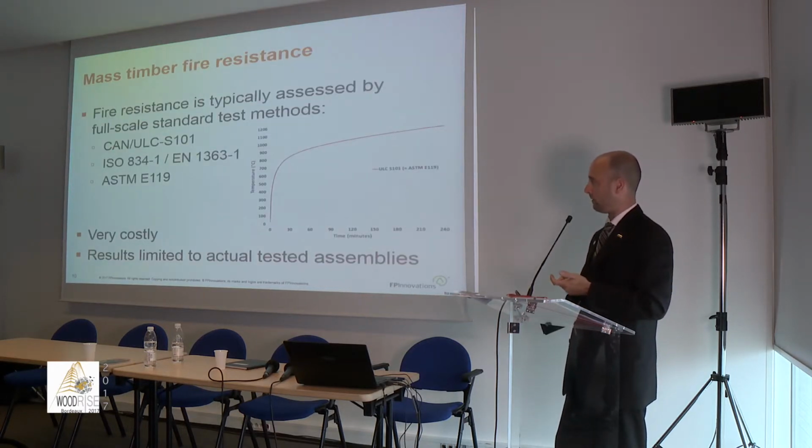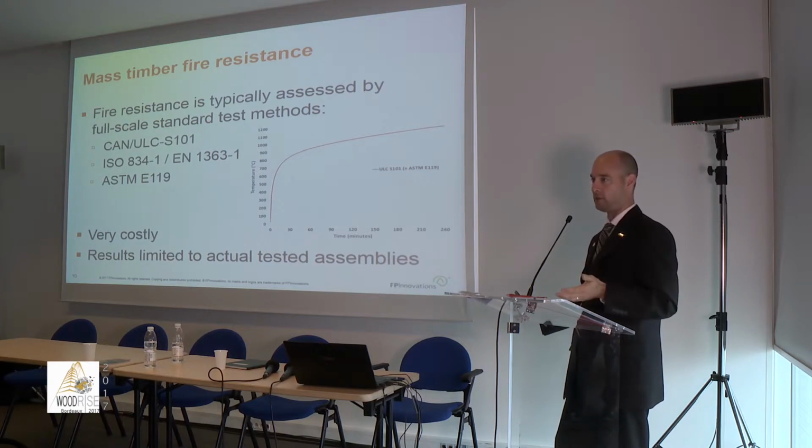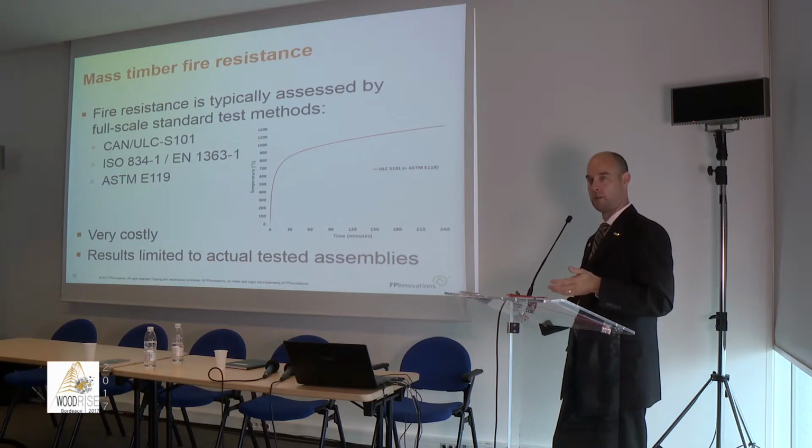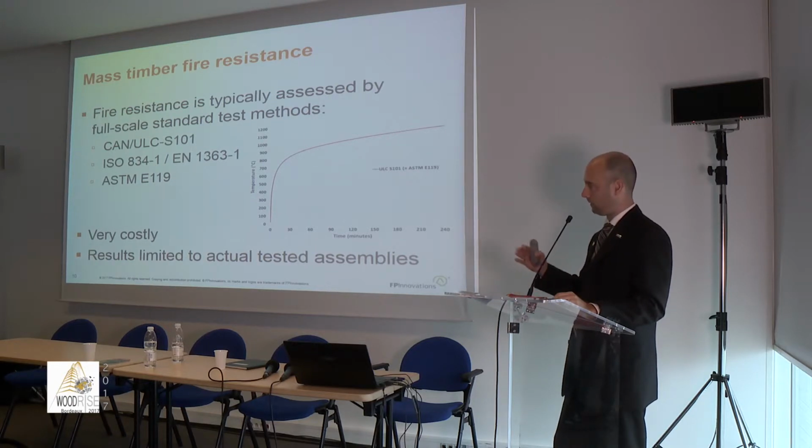So you have basically different tests. Typically, we assess the fire resistance of an element through a standard test method. There's the ISO test method. In North America, I have the ULC or the ASTM, depending on Canada or US. And in terms of fire severity, they are all very similar.